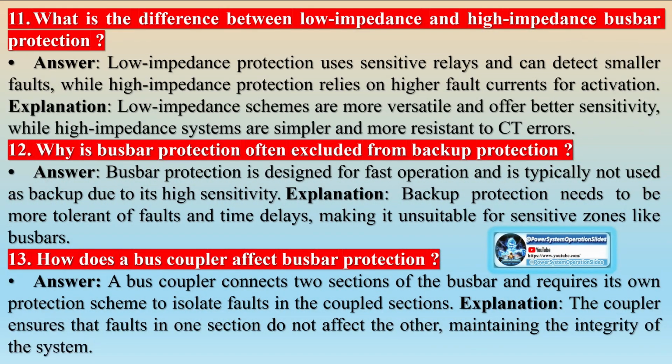This can be done using feeder distance protection with a fast discriminative reverse zone 3. When activated, this zone should trip not only the local circuit breakers of the feeders but also other connected circuit breakers, e.g., transformers and shunt plants, via a separate cross-tripping scheme. The time setting for reverse zone 3 must be properly graded with all feeder distance protections to ensure quick busbar fault clearance without tripping for faults within zone 1 of the feeder protections.